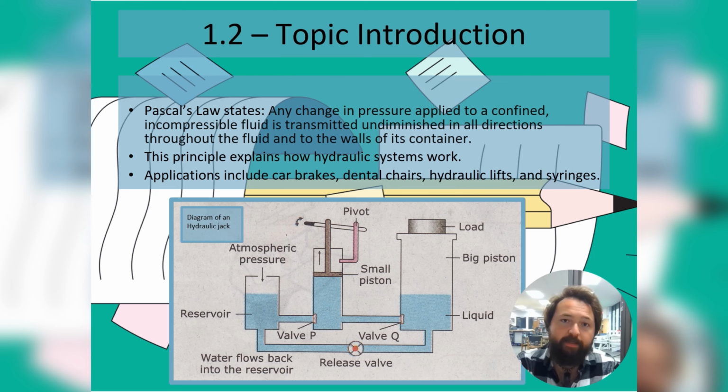Pascal's law states that any change in pressure applied to a confined incompressible fluid is transmitted undiminished in all directions throughout the fluid and to the walls of its container. In simpler terms, if you apply pressure to a fluid in a closed system, the pressure spreads equally everywhere inside. This principle is the foundation for hydraulic systems. Some everyday applications of Pascal's law include car brakes, dental chairs, hydraulic lifts, and syringes.